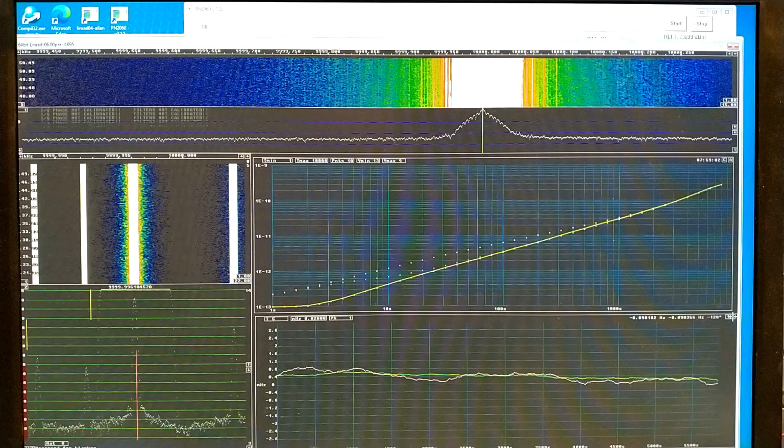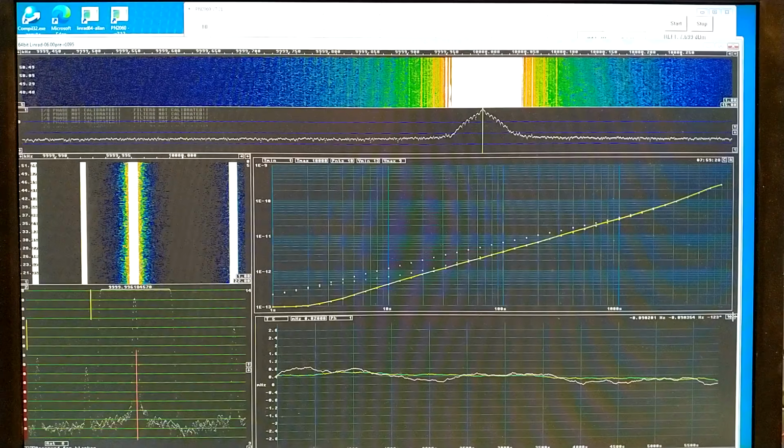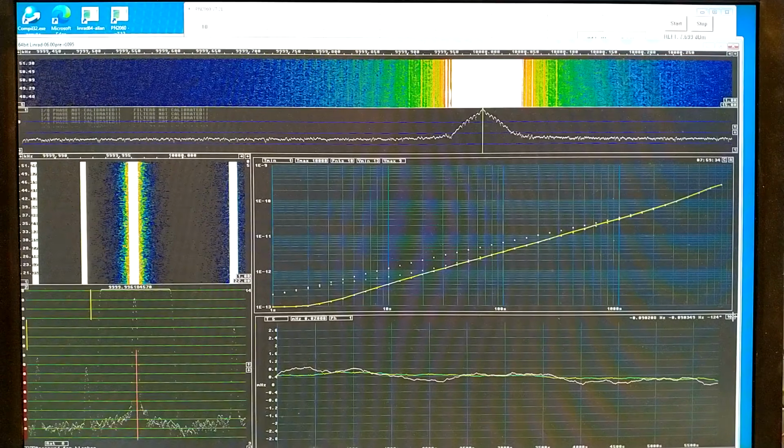It seems something inside the box is chaotic when it changes size due to a temperature change. Means it doesn't change size continuously. It makes some small jumps in size. And size means capacitance if it is some sensitive part. I will put a light source inside the box and shine light on various things to heat them a little to see if I can find where the problem is.